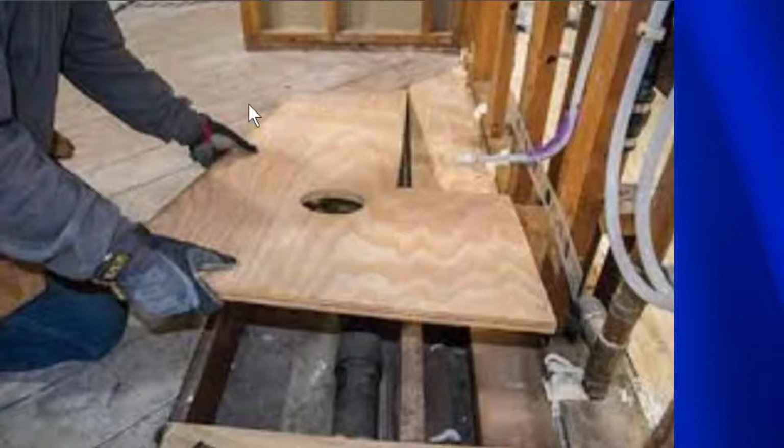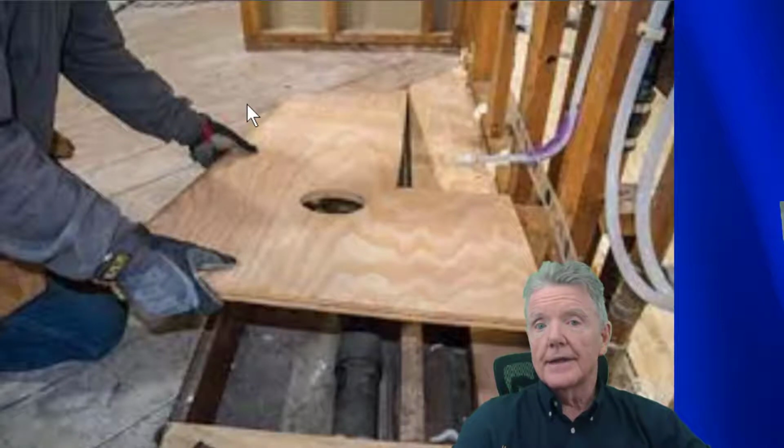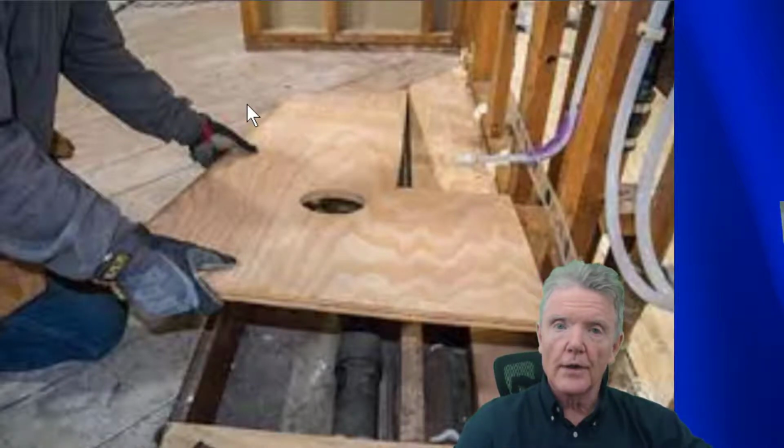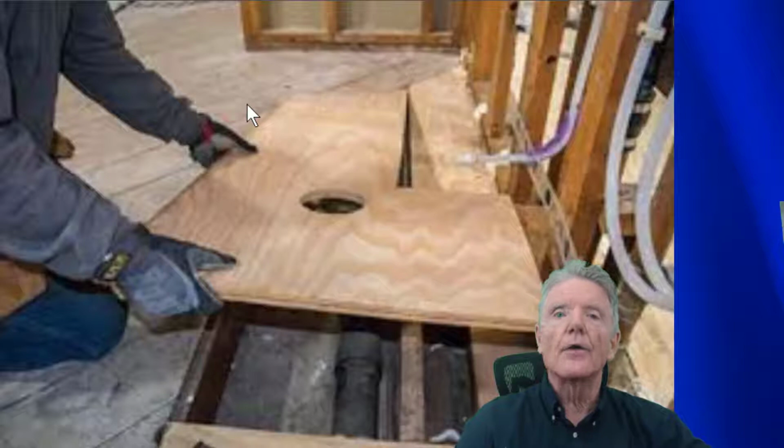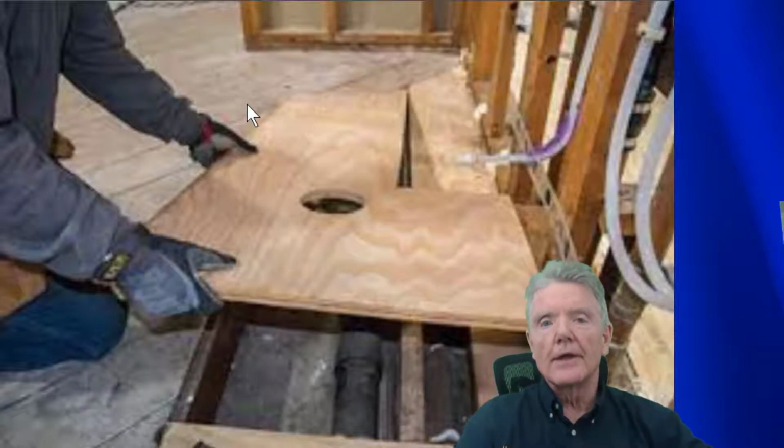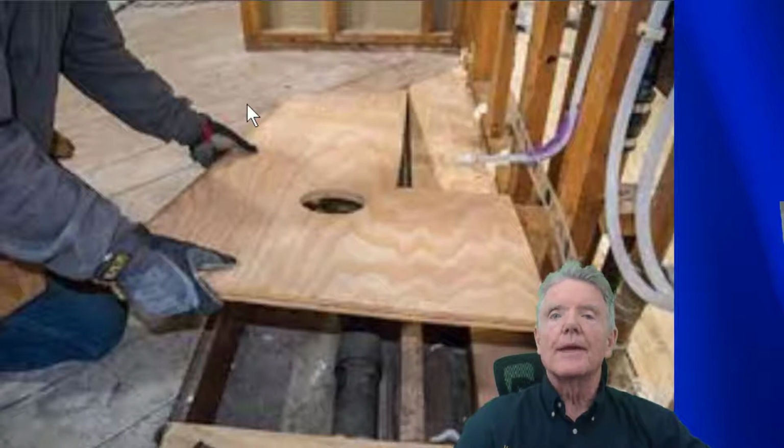This whole thing is diagonal boards. That's called diagonal sheathing, and diagonal sheathing is actually a rated shear wall material for walls, and it's very strong. It resists earthquakes pretty well, and it transfers forces out to wherever the foundation might be. So that's why these floors are very important to keep intact.